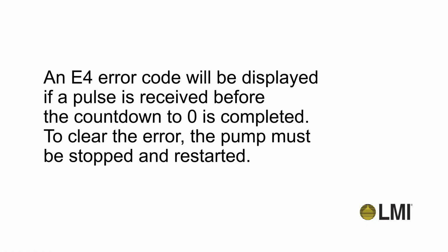An E4 error code will be displayed if a pulse is received before the countdown to 0 is completed. To clear the error, the pump must be stopped and restarted. See instruction manual for more details.